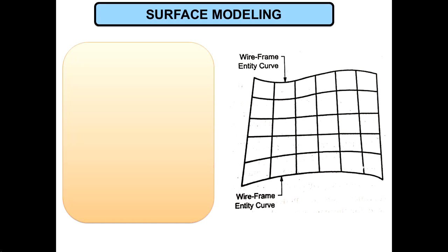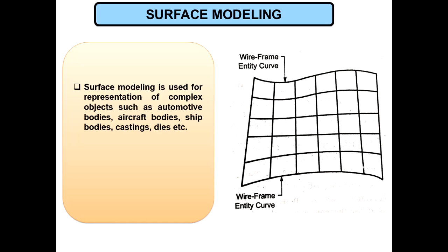Then let's see the second method of modeling, that is the surface modeling. Wireframe modeling is the basic modeling, so it is not used in today's software for modeling because of its various limitations. The second method, the surface modeling, is considered an extension of wireframe modeling. So from the wireframe modeling or from these basic entities, we can generate the surface model.